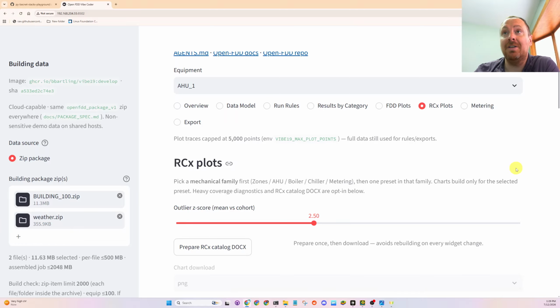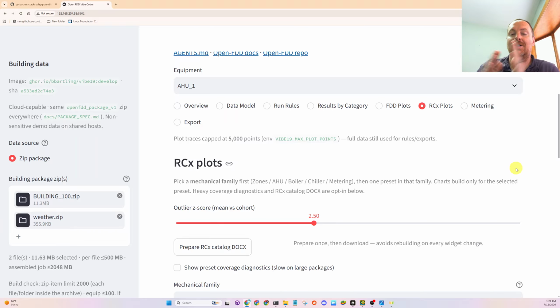So in retro commissioning, we just study how the building operates over time, which I was explaining in some of the earlier videos. The most ideal thing we'd be looking for is how the building operates in peak heating season, peak shoulder season for free cooling, and then another special reporting period during peak mechanical season. So like 3 periods during the year, and ideally we'd be reporting in all 3 of those phases.